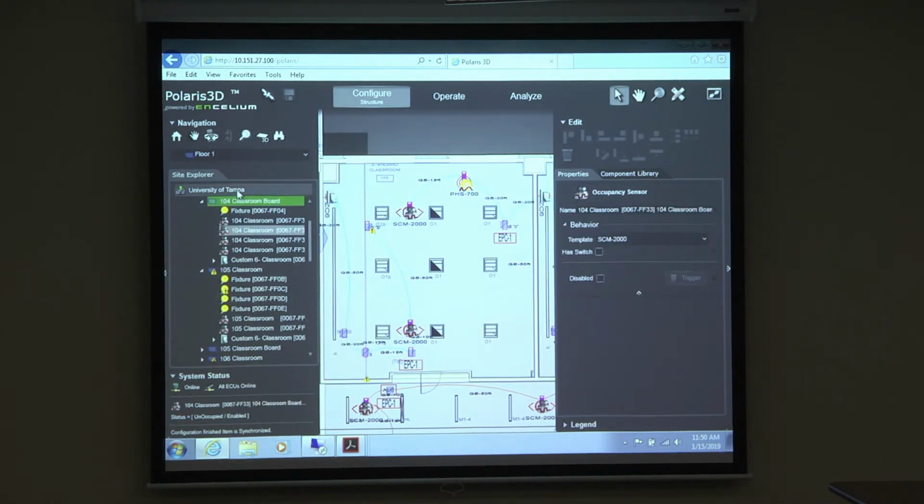And just for the record, when it says fixture, it's not the physical luminaire, it's the module device. So the LCM or the ALC or the PCDM, that's what it means when it says fixture, not the actual device. Because those devices are interfacing, they're like between. So the system here, the module, and then the fixture is attached to the module, right? Through those 2 black wires. So the power, and then going to the ballast, right? So that's interfacing. Similar to the SIM, the sensor module here.